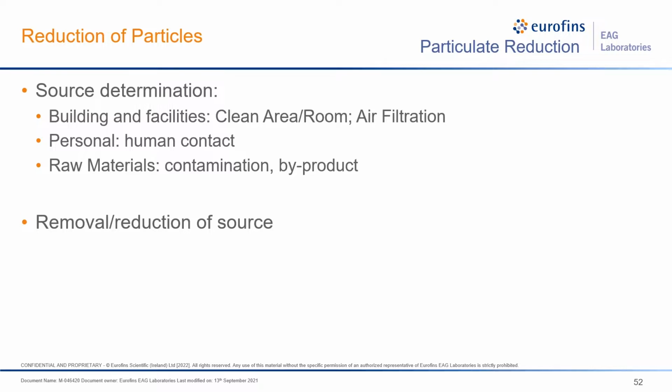So if you have a facility, is it in the clean area, is it a clean room? If it's a clean room, is it contributing from air filtration or not? The filters sometimes could be a source of contamination. So personal contact, human body, like I said, PDMS is in our makeups and hair gel, and our hair by itself and dead skin will contribute to particulates sometimes.